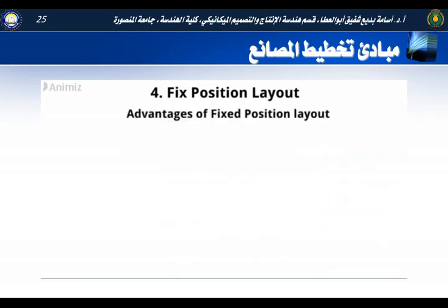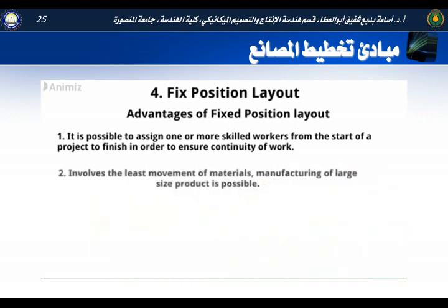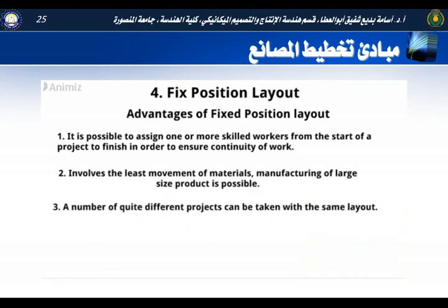Advantages of fixed position layout. 1. It is possible to assign one or more skilled workers from the start of a project to finish in order to ensure continuity of work. 2. Involves the least movement of materials; manufacturing of large size products is possible. 3. A number of quite different projects can be taken with the same layout.